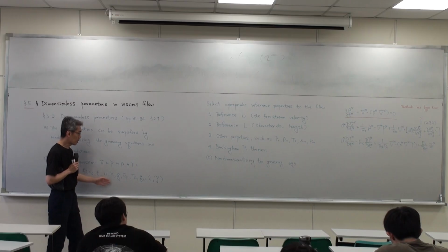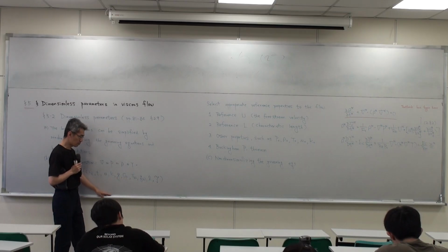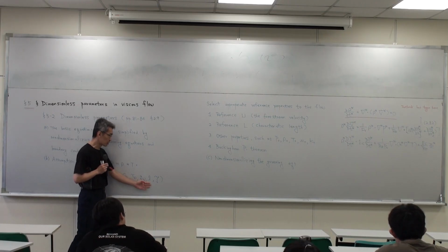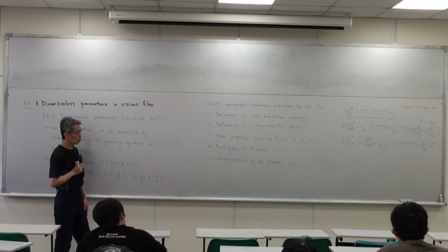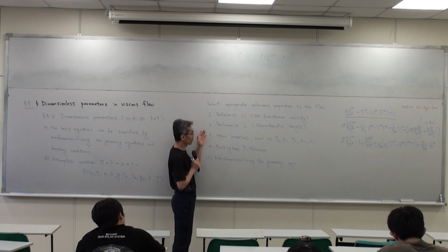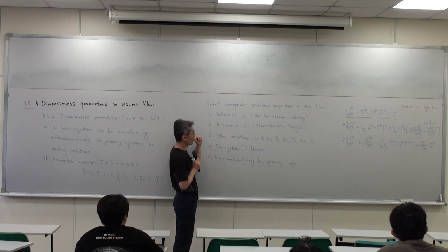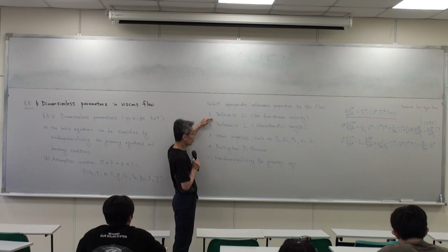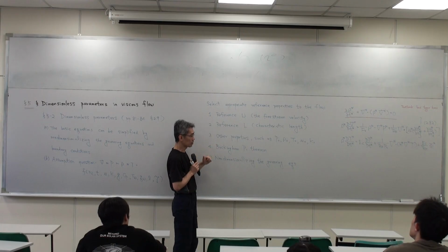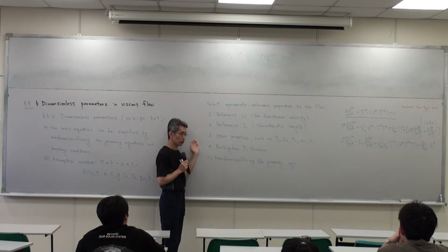Then other parameters, maybe you can look at the textbook, like the heat condition, or the slip condition, or different kinds of force. Then, if we want to make the governing equation and the boundary condition non-dimensionalized, usually we need some reference property: reference velocity or reference length, which are the most important. Other properties, like reference pressure, maybe reference density, we sometimes use.